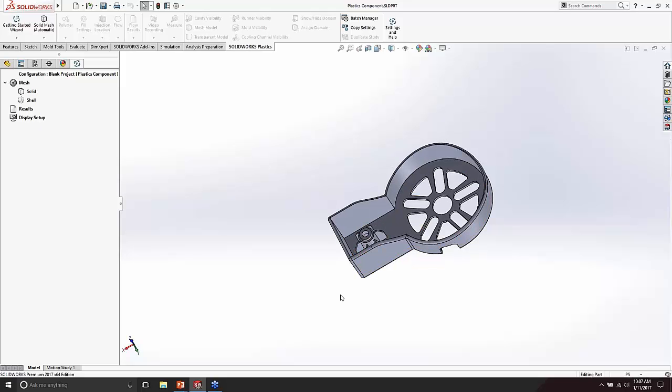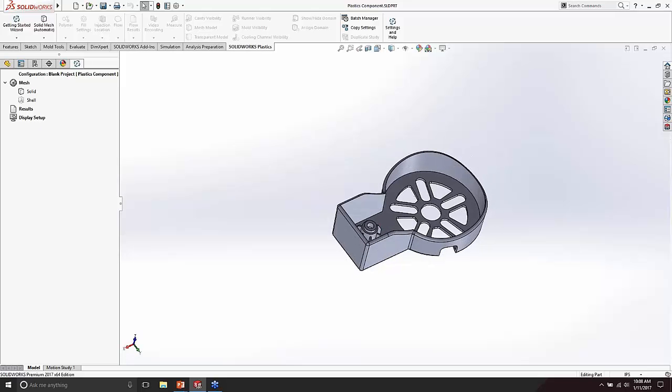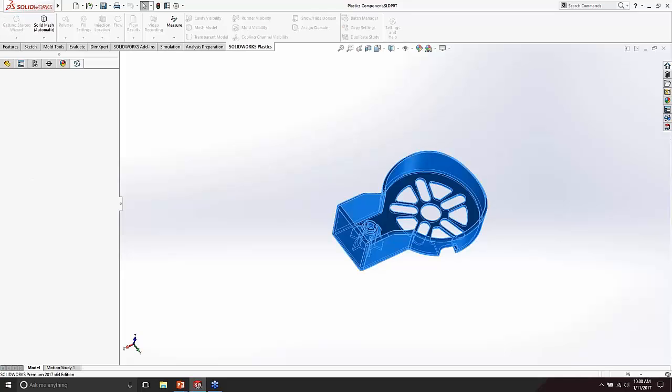What I do is I first have to define this body, letting the SOLIDWORKS software know that I want to inject a molten plastic, that fluid volume, into this space, what's taken up by this model here for us. So I'm going to create a mesh. The mesh is capturing this entire body, letting the software know exactly what it's trying to accomplish. We'll go ahead and start with just a simple mesh here for us. We'll do a shell mesh.